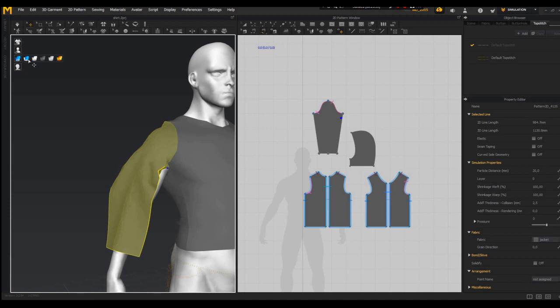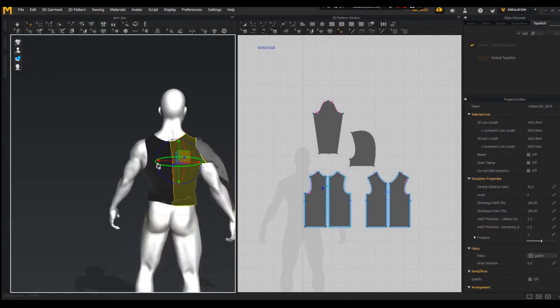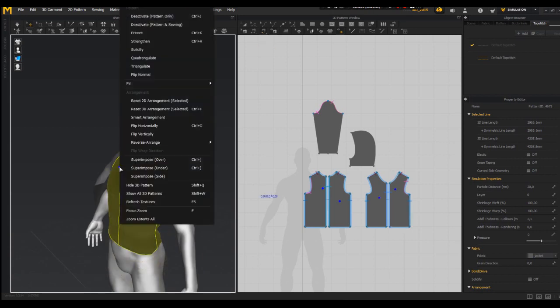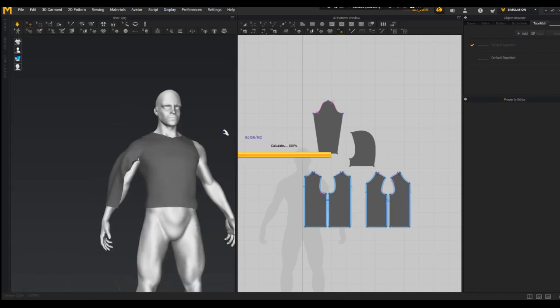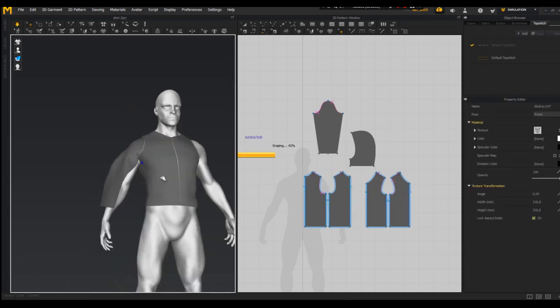Sometimes check your normals. For this, go to the texture surface mode or Alt plus 2. If your normals are flipped, it will be shown. For example, here we have such a problem. In general, you can always work in this mode. It's not prohibited to do so and perfectly okay. It doesn't show the thickness though, but overall it's fine.